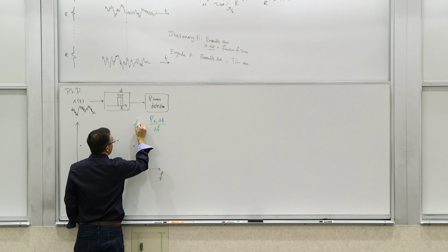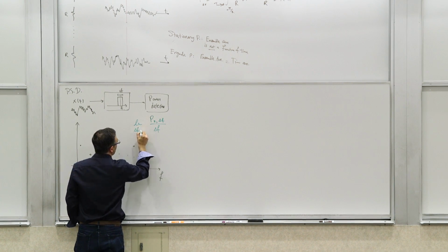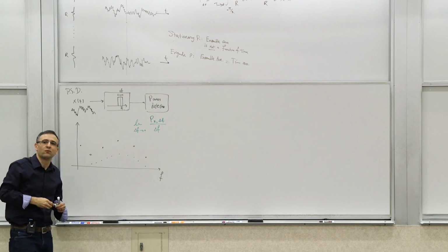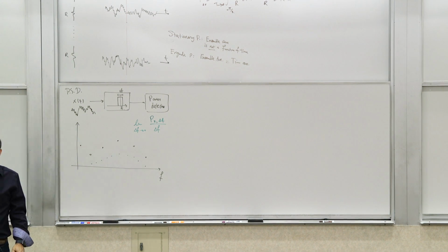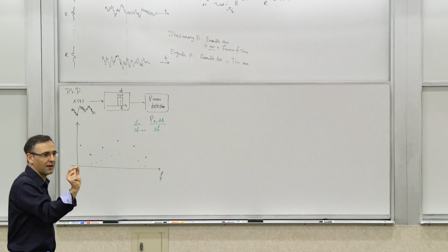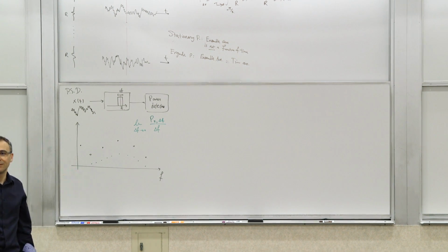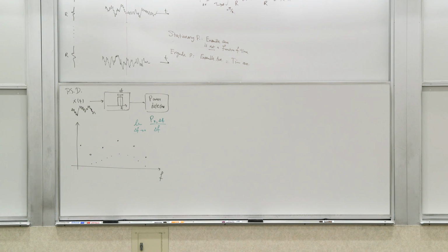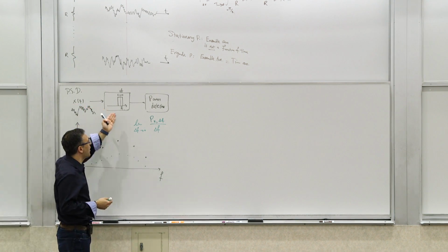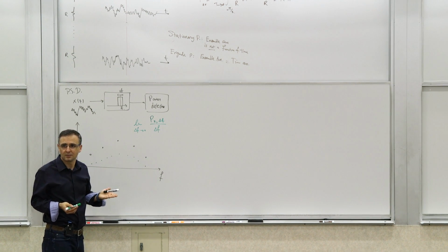And then in the limit, we really want delta F to go to 0. But if it makes you feel better, imagine that if 1 hertz is sufficiently small bandwidth for your application, you can say, well, I take a 1 hertz filter and move it around. But in reality, you're taking something that's infinitesimal and moving it around, because that allows you to deal with things that are sub-hertz and all those things. But what will come out will have units of whatever x units are per hertz, right?